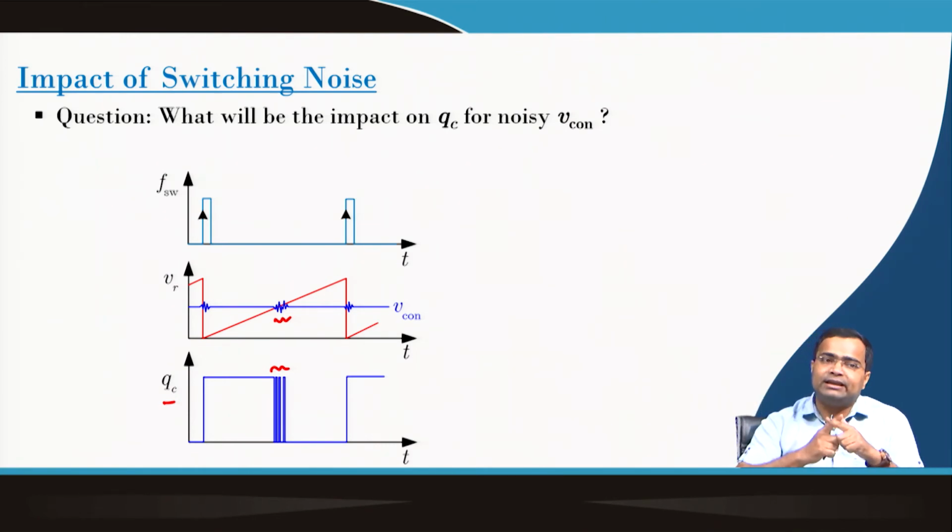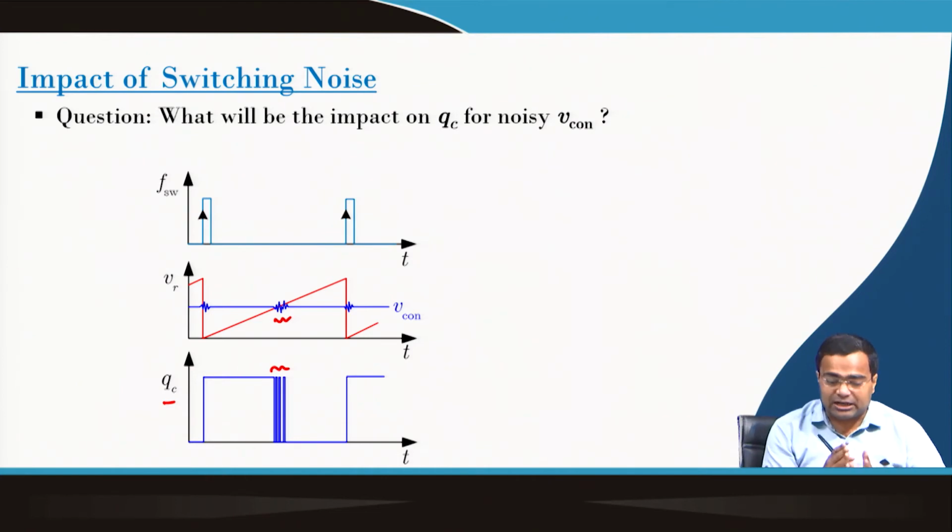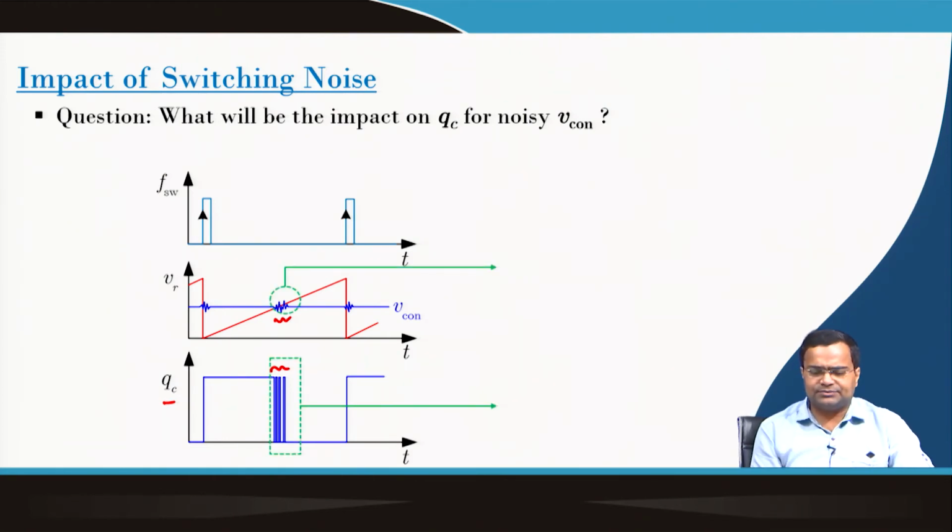Similarly, if you try to hit the limit in its rise and fall time, it can get heated, and if you continuously do that, it can even damage the MOSFET. Okay. So, such chattering is not recommended, and we should not allow it to pass to the gate signal. Then how to avoid chattering?